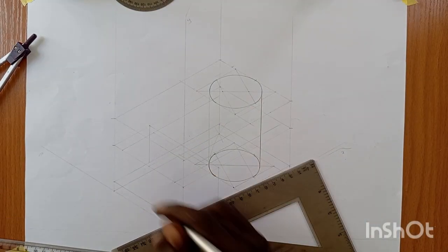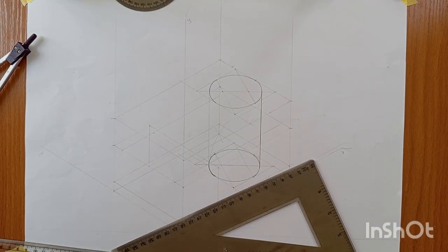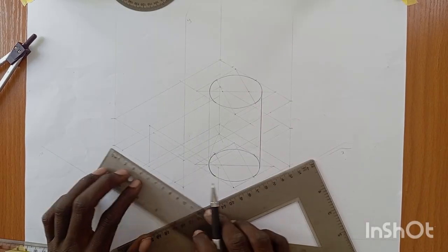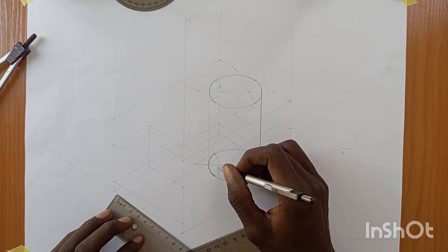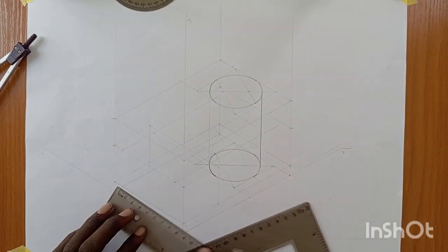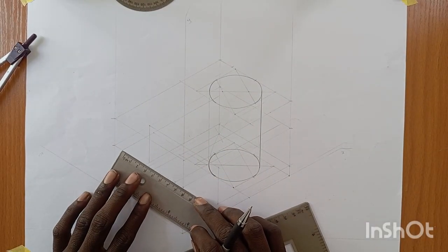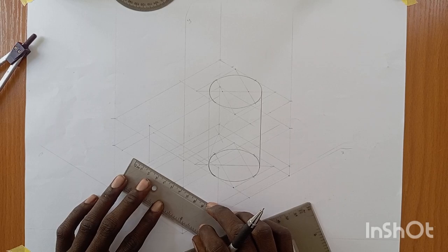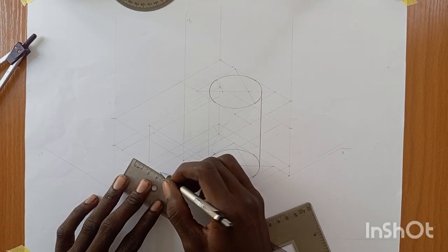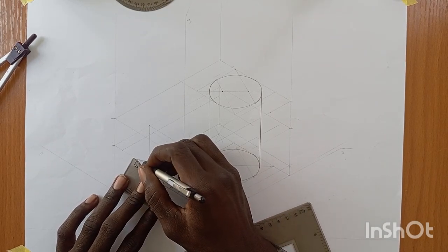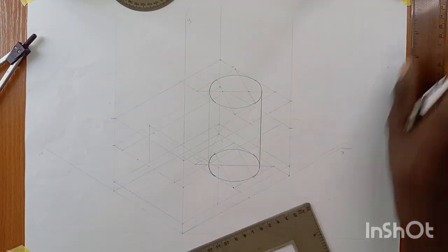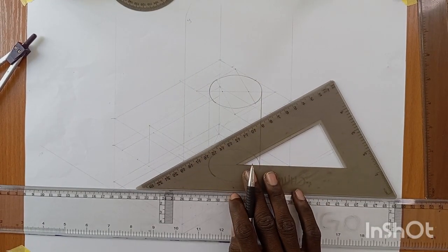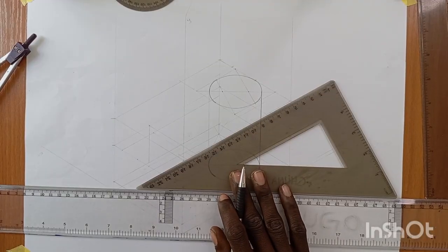Now, from this line, you are going to take your 15 upward and 15 downward. As you can see, this line bisects through this line, right? Let me take 15 from here. It's more clearly seen. You can take it here. Because this has entered into the line, so it might be confusing. Let's do it here. The total is 30, right? So now I take 15 here, this to 30, 15 here. And that is it. I do this simultaneously to make my work faster. I can take 15 on one side and then 15 on the other side, but if I take from any point and then take from here up and down, it makes my work faster.